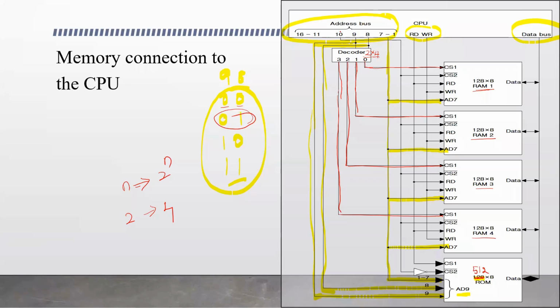And what is this bit 10 here? We have seen the least significant 1 to 7 bits of the address bus, and bits 8 and 9. Now about this 10th bit. The 10th line is connected as the second selection input, CS2.